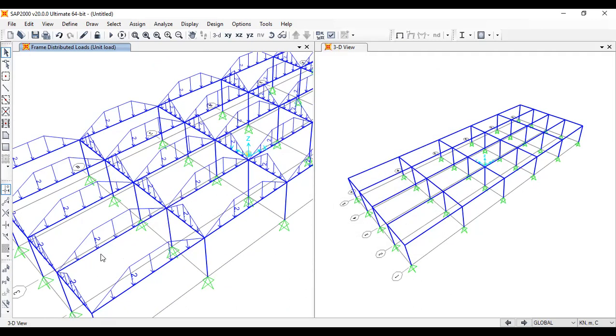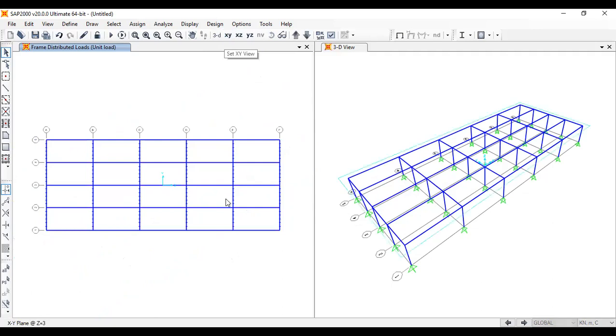From this panel is, so for interior beams, not along the edge, for interior beams, this load will be doubled, right? From this panel and the next panel. So we have to select that. So for this beam, it will get doubled, right? So load from this part and load from this part is added.